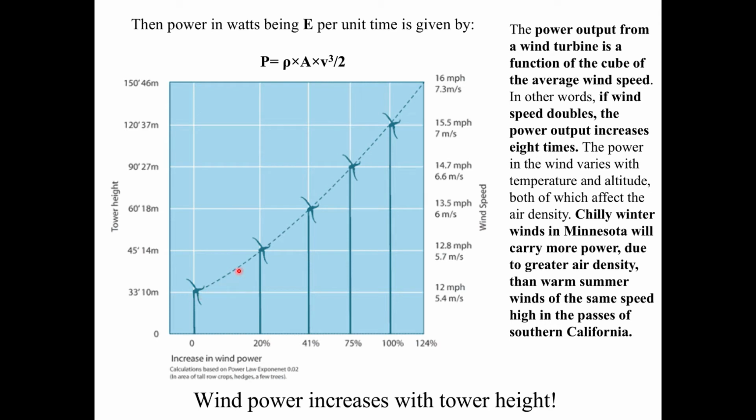One of the things that engineers do when they are siting wind energy infrastructure is they make measurements, often for several years in a particular area, using an instrument we call an anemometer. And an anemometer measures wind speed and wind direction simultaneously. That's all captured digitally now, so you know by the second, every minute, every hour, every day, every week, every month, over a number of years, how the wind speed varies both in terms of speed and direction, meaning the upstream direction.